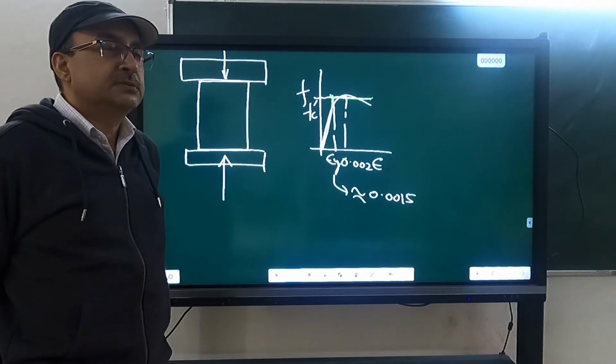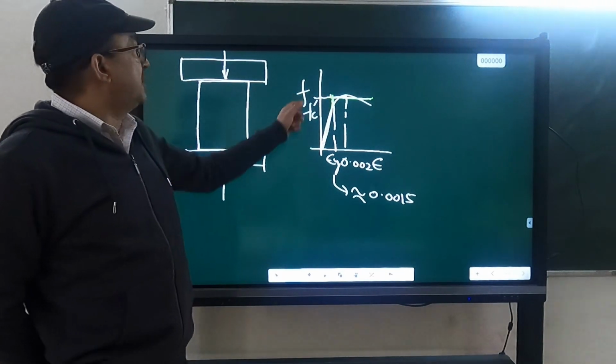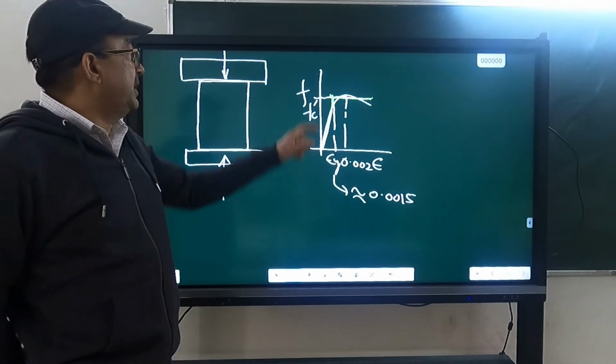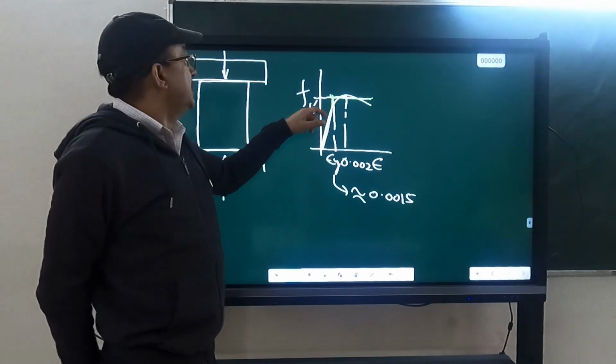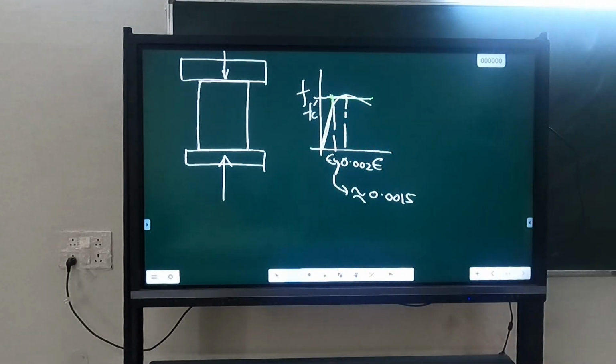Yes, but how can you ensure that the point is coming before 0.002? You can see that if the area of the two curves is to be equated, I can't take it up to here. At 0.002, cracking is forming. Actually, micro cracks start much before 0.002. Then at 0.002 the cracks develop and become visible, and then the cracks expand, and thus the concrete strength goes on reducing.